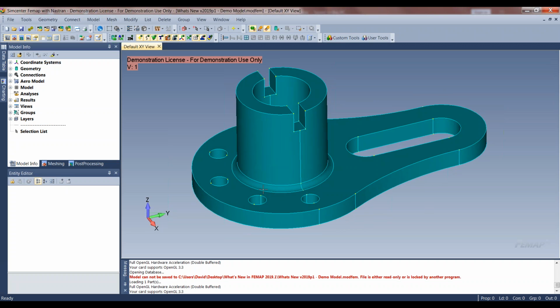So what we're going to do today is I'm going to slice the solid, and then we're going to mesh the bottom plate with hex elements and show you some new functionality there. And then the cylindrical body we're going to mesh with tetrahedral elements. And I'm going to show you how to transition. This is a new functionality in the latest release, transition from linear hex elements to parabolic tet elements, right? And why would we do that? If we wanted to capture the curvature in this fillet, because it was a critical stress area sometimes, but it's nice to have nice hex mesh on a nice uniform plate like this.